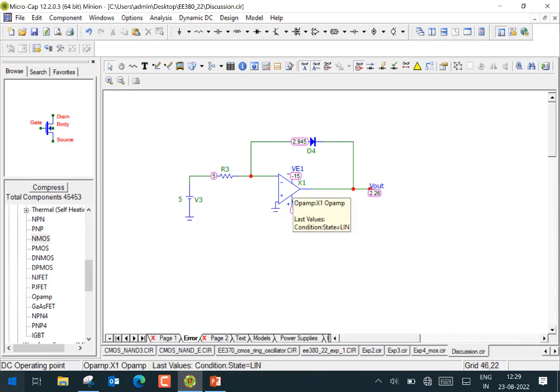They took out the op-amp. Okay, guesswork. Well, probably the resistors don't go bad. Diode is also very robust. Maybe the most unreliable component in the lab is the op-amp. So take it out, right? Also, it has more connections. Maybe you have not inserted it properly. Take out the op-amp and they put it back. And again, the same thing.